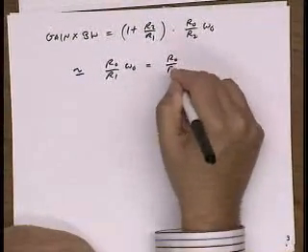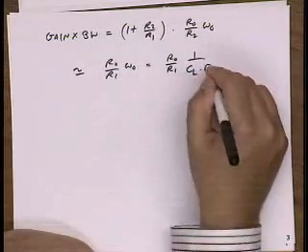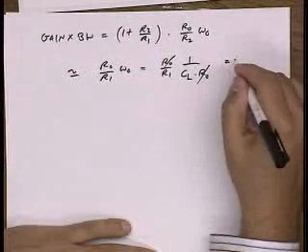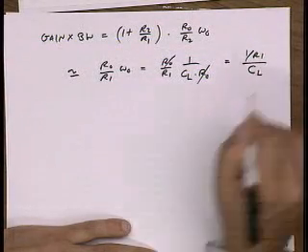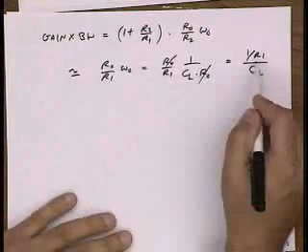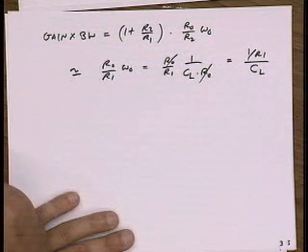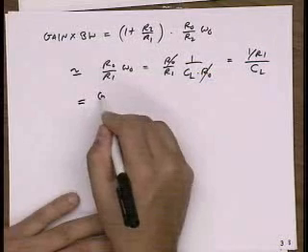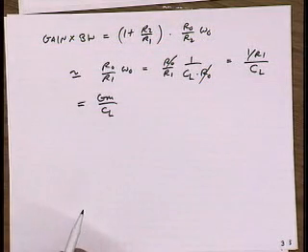And remember, omega naught is just the capacitance at the high Z node times R naught. So actually R naught cancels out, and I get a nice expression, which is that the gain bandwidth product is 1 over R1 divided by CL. Okay, so this kind of looks familiar, right? It looks like a transconductance over capacitance. For a voltage amplifier,